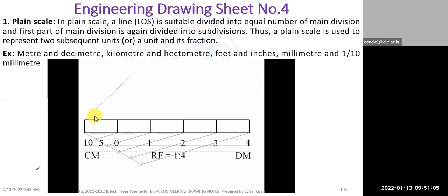Now, these arcs that I'm going to draw are of 5 millimeters. You can always change the arc radii. That's it. 1, 2, 3, 4, 5, 6, 7, 8, 9, 10. Now let's join this point with this point, since this much is the portion that we need to divide into 10 equal parts. Now you can keep your trapezoid over here.